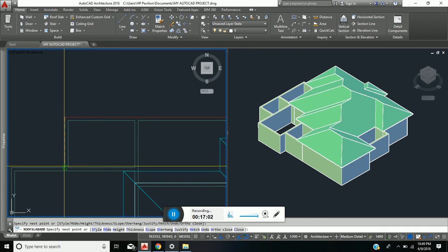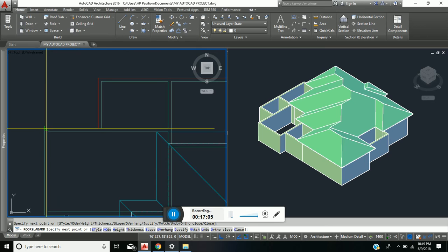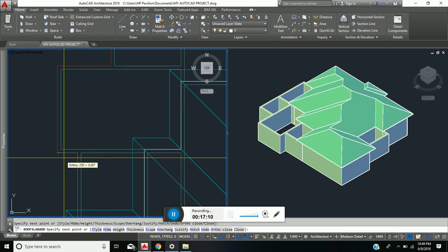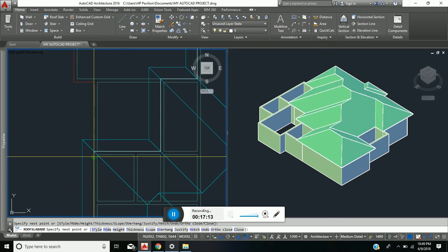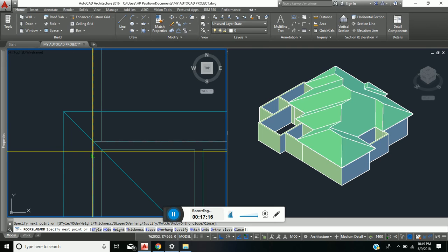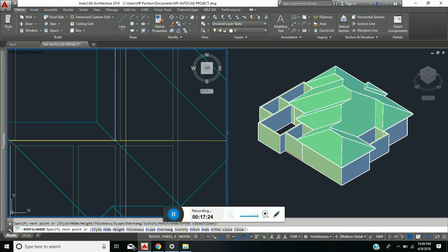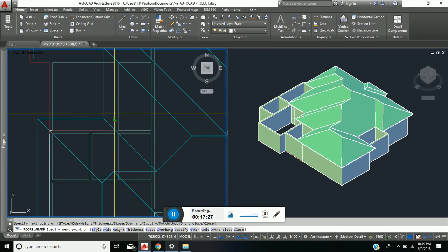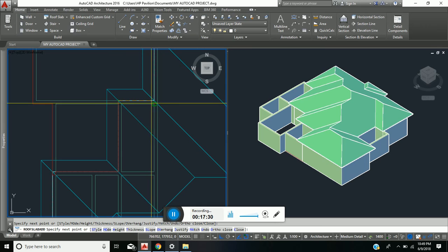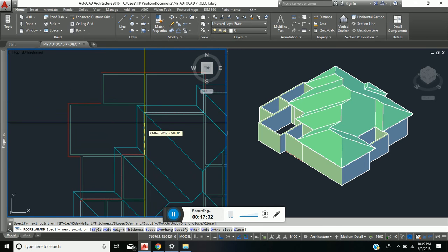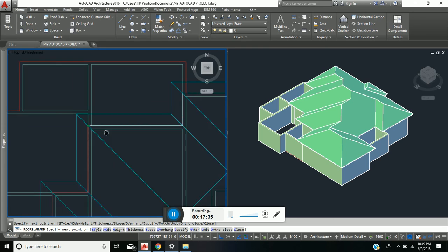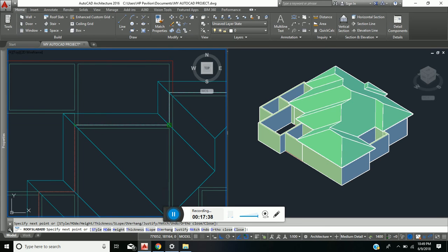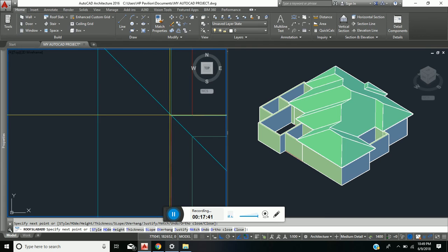Again, I am careful to ensure that I select the outer corners that the slab is expected to cover. When I get to this corner here, I'm going to pass just a little bit, say to here, then I'm coming back in here, and I'm going to be following my original polyline because those are the corners that the slab will be visible in from the inside.